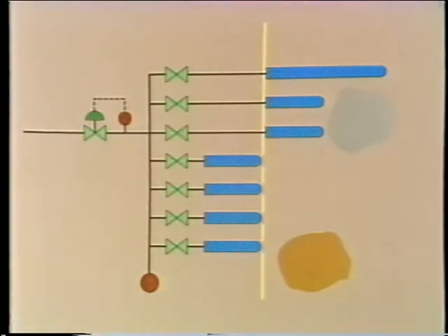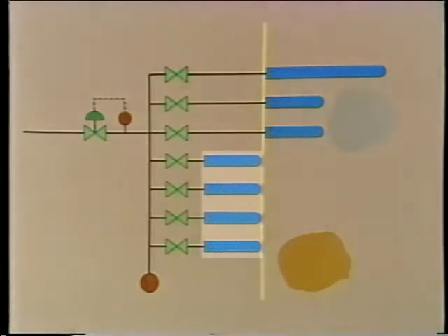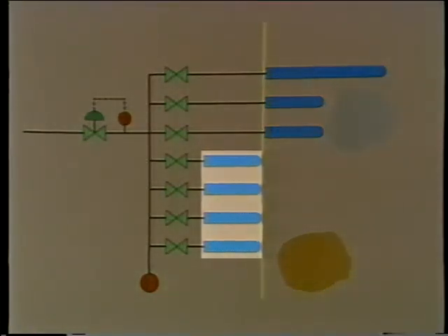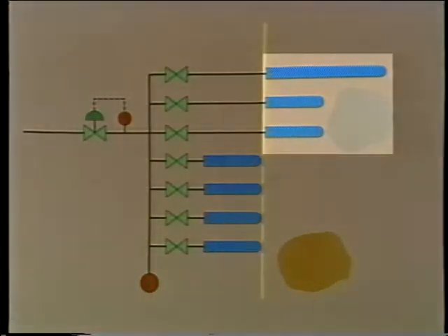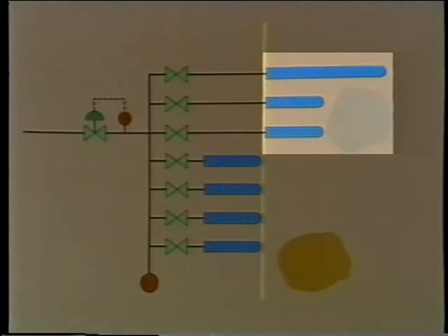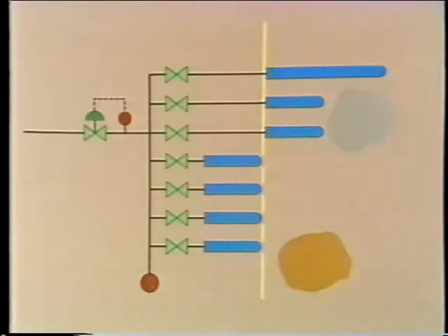Most boilers use a combination of 2 or 3 types of soot blowers. Where retractable soot blowers aren't necessary, it's more economical to install less complex and less expensive fixed or rotating soot blowers. As we've said, all these soot blowers make up an integrated system used to clean the boiler while it's in operation. Not all the soot blowers are operated at once. The operation of each soot blower is coordinated in a cycle that is part of a sequence. This sequence is designed to progressively clean off deposits and pass them out of the boiler.